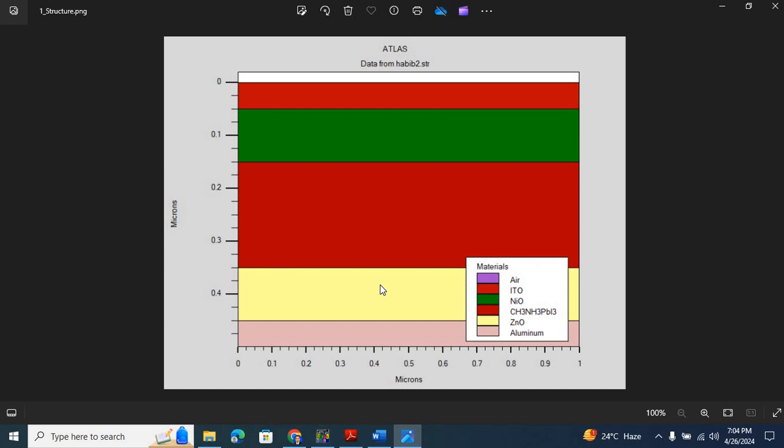Recently, perovskite solar cells have reported efficiencies up to approximately 30%. But despite its high power conversion efficiency, we cannot really make it totally organic because most of the electron transport layers and the hole transport layers in these fully organic perovskite solar cells remain sensitive to moisture. So a better idea is to use inorganic electron transport layer and hole transport layer suitable for these devices.